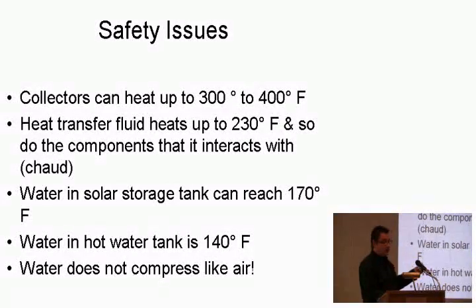I said, if you get enough sun where you can keep the water temperature hot enough in your solar storage tank, you're fine. But if you have 3 or 4 or 5 cloudy days and you use a bunch of water and that temperature drops down in your solar storage tank and you don't have a hot water heater to bring that temperature up, it won't kill those bacteria. So you might be having an expensive trip to the hospital, and I think it sort of clicked in. But I said, that's your choice. I'm just telling you, there's no actual bypass, and you could put a bypass in to bypass your hot water tank. But generally, it feeds your hot water tank as a preheat.